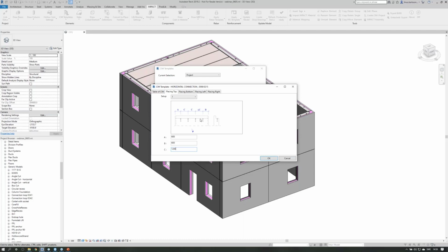And then one of the spacing needs to be a little bit smaller or bigger, since it's not possible to get even values all the time. Then I want to have the same in the bottom, and here I got this 0599 custom material. So I have the same because I want them to align in the bottom and the top elements. And then the sides that I want them to place, I just zero them out like this.